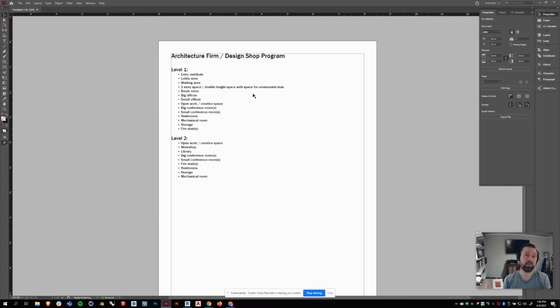So your bays are 24 by 24. If you left a 12 foot by 24 foot space, roughly, cut that bay in half. That would be a good fire stair size to get people from level 2 down and out. Ideally on an exterior wall. In fact, it will have to be on an exterior wall.